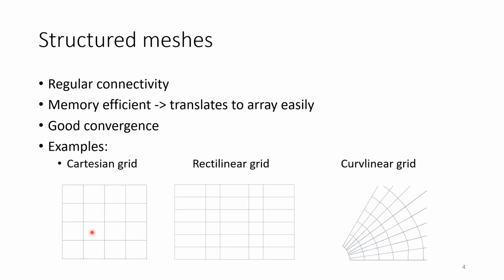We will talk about this in one of the following courses, which simply means that the solution usually is quite smooth, solvable, right? The Cartesian grid is, I said, the simple one. It doesn't need to be that simple, right? We can have different element sizes and I can still store this in a 2D array, right? I would still need additional information knowing the width and length of each element, but that's okay. I can do that, right? Or you can also do something like this, like a curvilinear grid. Still, my neighbors are well defined for every cell.